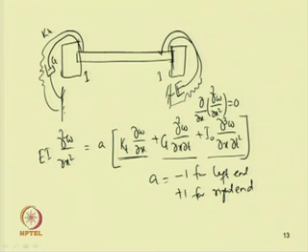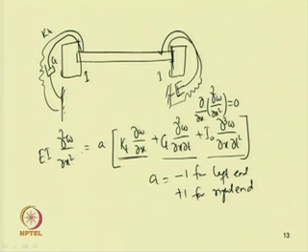So, one can similarly derive the equation of motion or temporal equation of motion of the system by taking a shape function which depends on the boundary conditions. For different boundary conditions, by using these expressions, one can derive the shape function, and after using those shape functions one can reduce the governing equation to that of a temporal form.